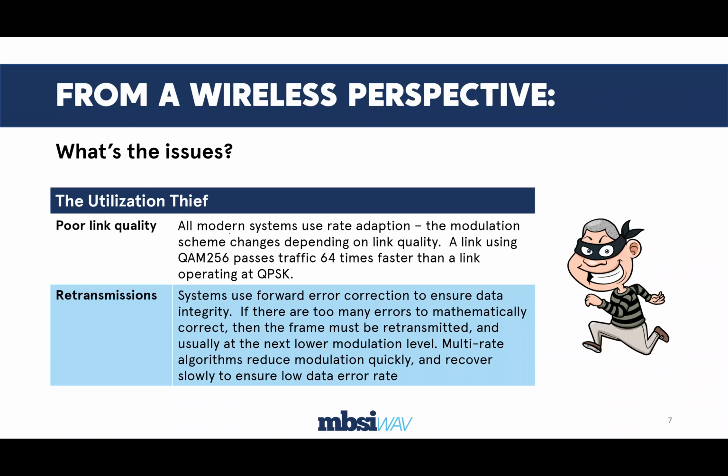So we have kind of a conundrum here. We lower the modulation level to reduce the signal to noise ratio that we need to recover the data, but at the same time we do that, we're forcing ourselves to use the medium longer in order to pass that traffic. And so poor link quality is a utilization thief.